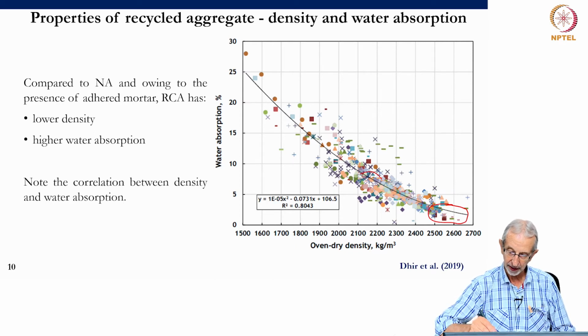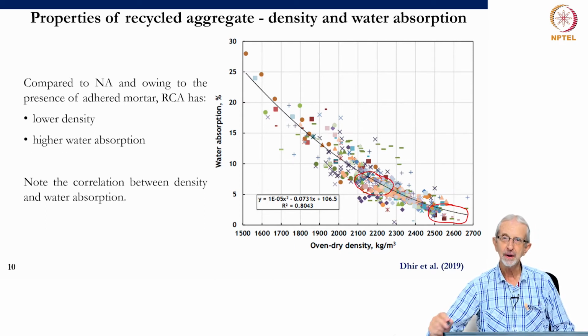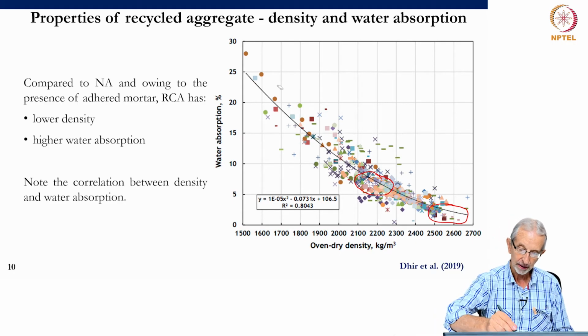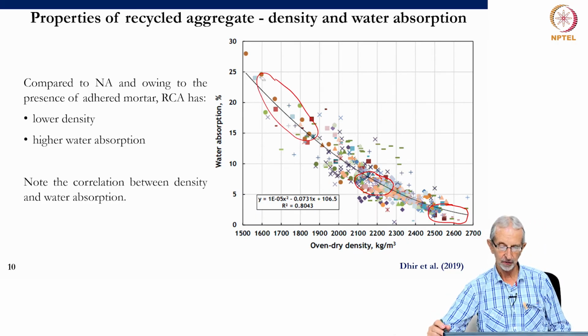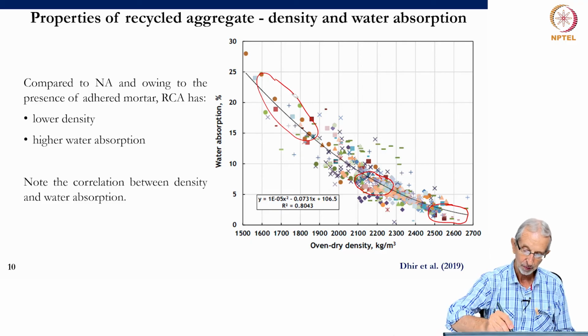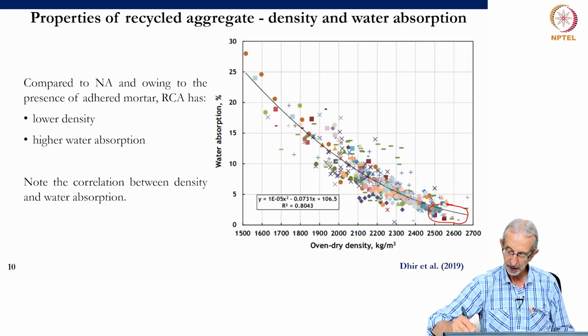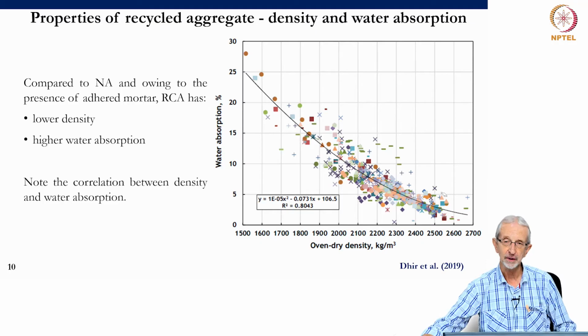Whereas the fine aggregates would tend to land up here, together with some of the poorer natural aggregates maybe, where you do get occasionally high absorptions. And then clearly right up here, we're up to the extremes, where 20 or 25% absorption is probably not something that we really want to work with, because it becomes very difficult to work with that kind of material.